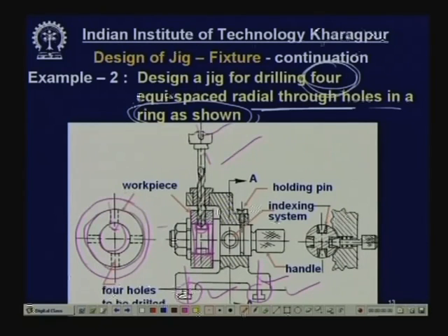So, after locating, now this axial location will be assured by this collar of the mandrel. So, this is the entire mandrel, one piece, and this is the collar which is resting against a pre-machined collar of the disc jig, and against this end face of the collar the job piece is located. So, this is not V block location, this is on mandrel. Now, after that, locating and supporting have been completed.